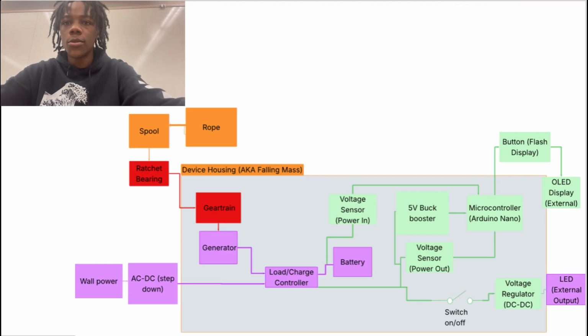The main hardware I worked with includes the Arduino Nano R4, an OLED display, and multiple INA219 current sensors that communicate over I2C. Within the overall system, my subsystem acts as a link between the power electronics and the user interface. The sensors collect the electrical data from different parts of the system, the Arduino processes that information, and the OLED display provides live feedback to the user.